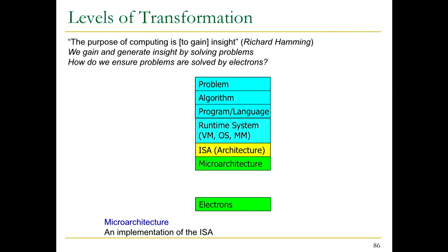That helps. So bit serial adder certainly is one way of designing it, and it's very simple, right? You don't need hardware that's large. On the other hand, a lot of the adders that we have today are very complicated. They do all of this in parallel. 32 bits, all of the bits are added in parallel.